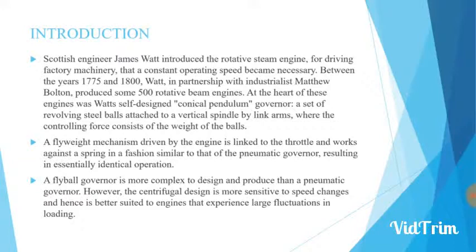A flyweight mechanism driven by the engine is linked to a throttle and works against a spring in a fashion similar to that of the pneumatic governor, resulting in essentially identical operation. A flyball governor is more complex to design and produce than a pneumatic governor. However, a centrifugal design is more sensitive to speed changes and hence is better suited to engines that experience large fluctuations in loading.